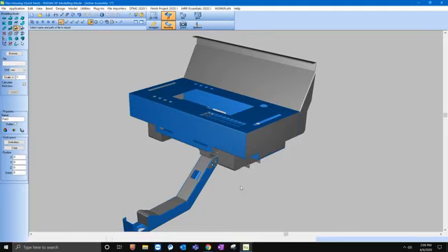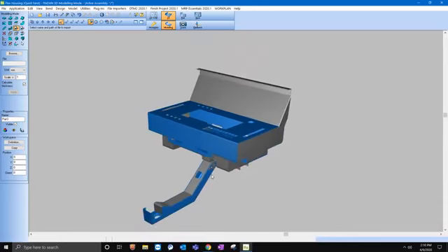So back to it. In the 3D environment here, this is where we modify and change our sheet metal, open our 3D sheet metal parts and move them into different areas of the software. Generally, if you come in, you've got the 3D software. I can move it into a nesting and create a nest on all these parts in the sheet metal property.